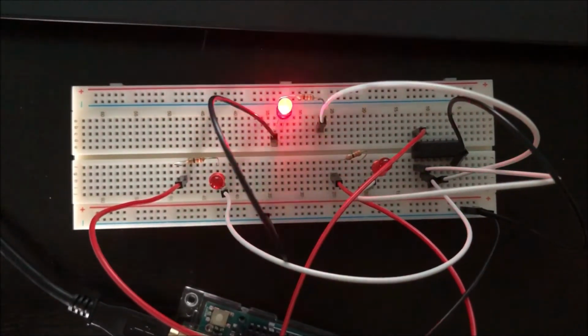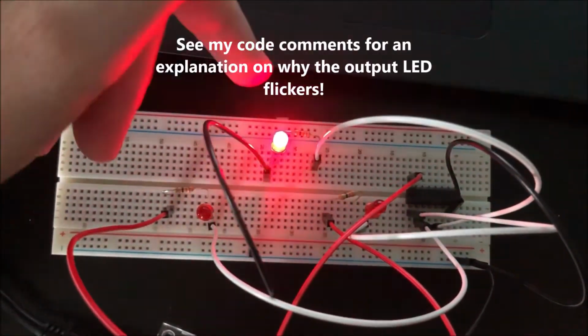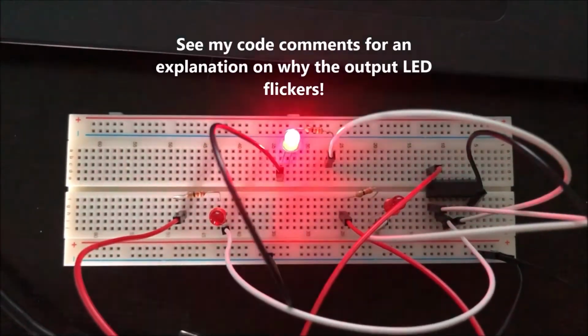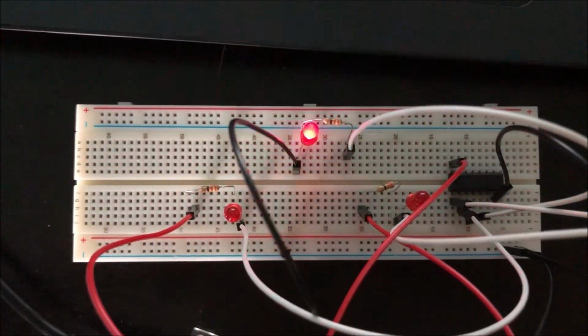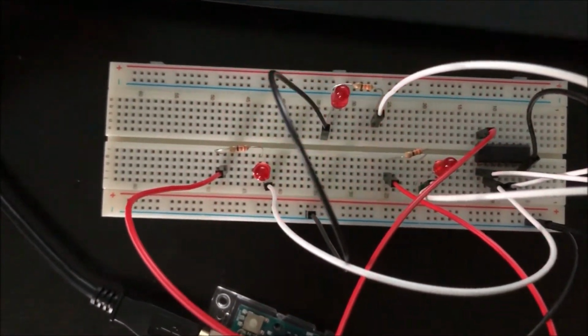So for the final creative part of the project, I hooked up an AND gate to the breadboard. As you can see, I've also added additional LEDs at the bottom left and up top. This LED on the bottom left uses an analogWrite command to fade it in and out. The LED on the bottom right uses the digitalWrite fade command that I wrote in the previous problem. They are hooked into an AND gate where they're each inputs, and the output will illuminate this LED.